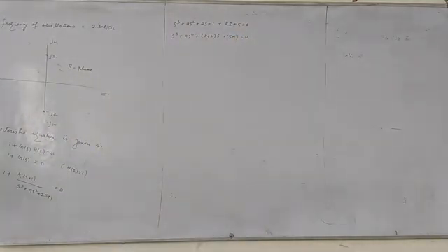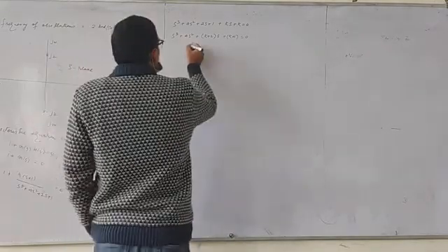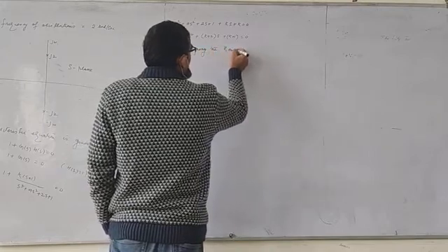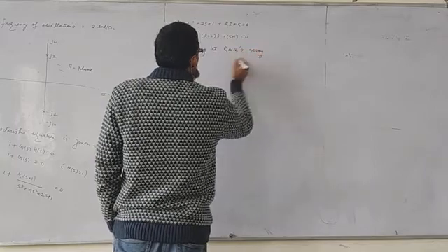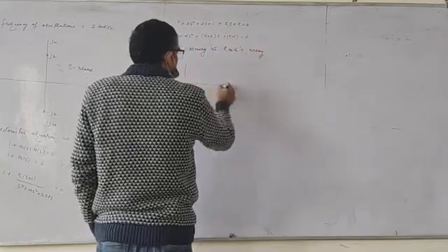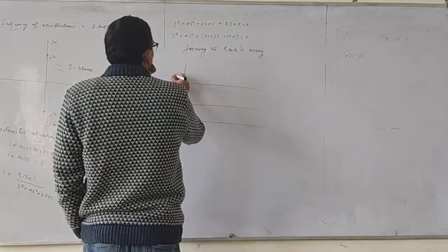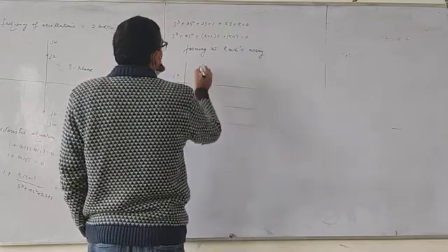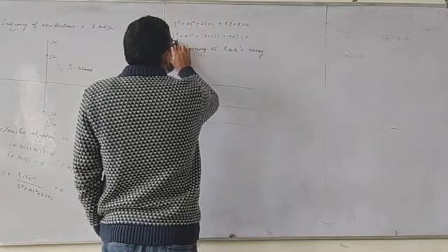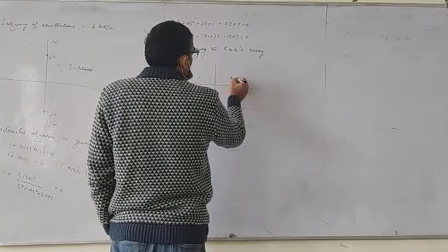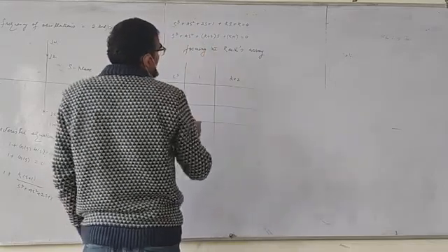Now what do we have to form? We have to form the Routh array. After the Routh array, the frequency of oscillations is given to us. I will make a note for that. Let's form the Routh array first. For s cube and s square, the first terms are 1 and a, then k plus 2 and k plus 1.